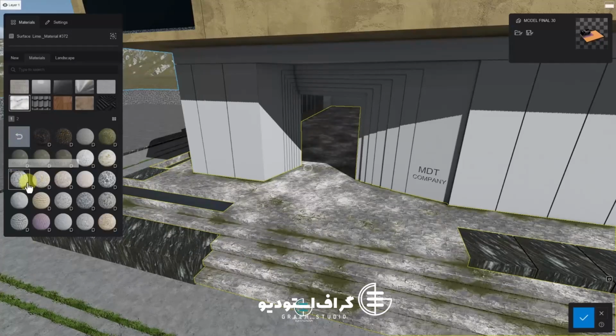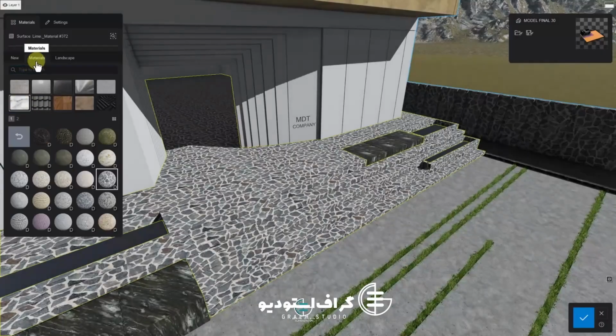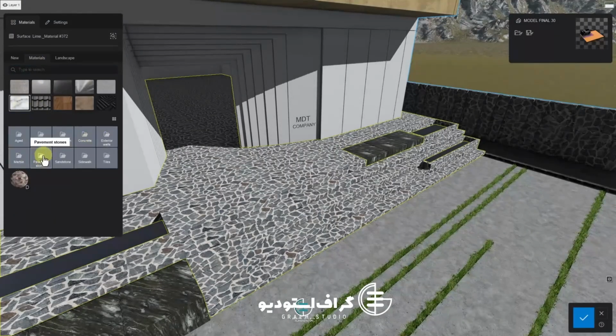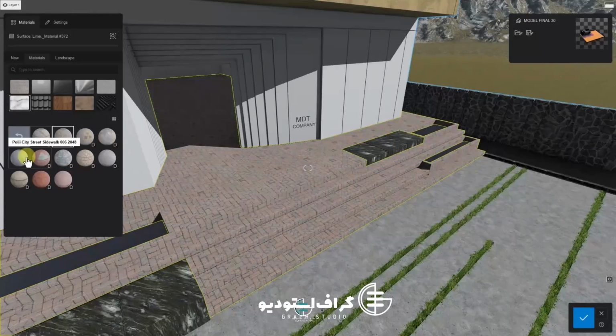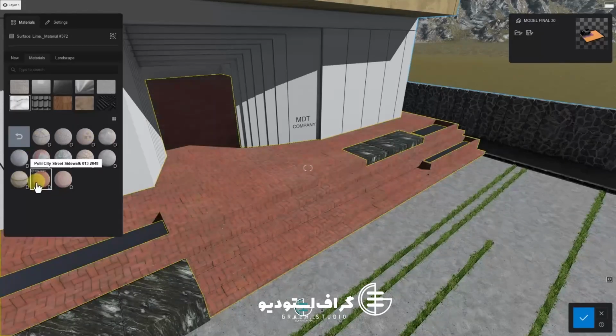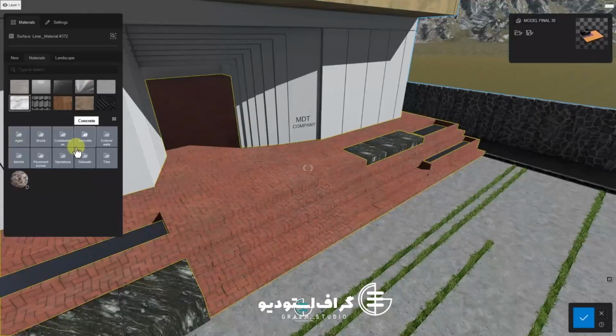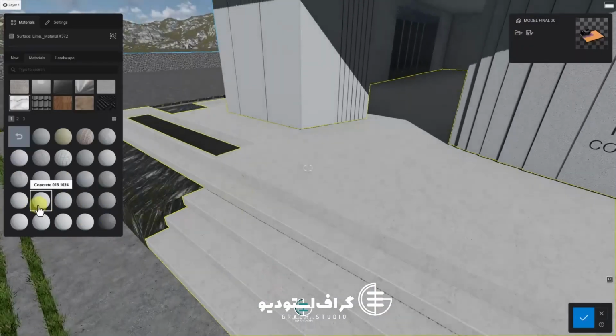I played with the contrast a bit in Photoshop. I created the normal map like this, the displacement map, and the roughness as well. See, they can all be created in Photoshop. I hit Edit Copy, and now I can import it here. I just need to give it a new standard material here and load the maps one by one.